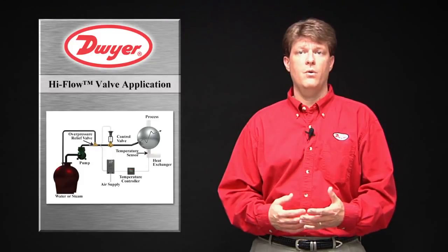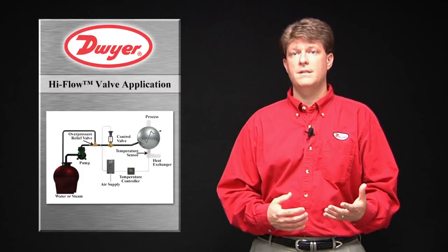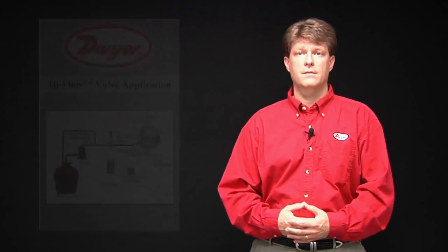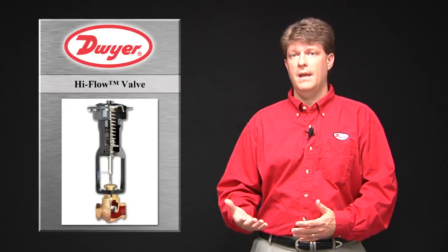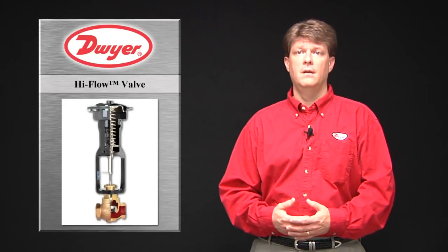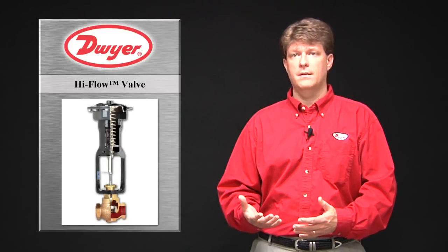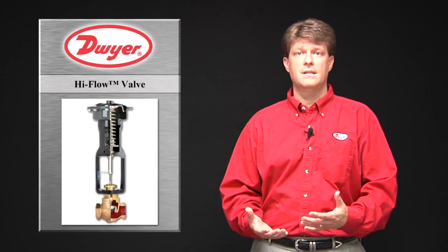In the example shown, a high flow valve is controlling temperature by varying the amount of steam or cold water added to the process. It is essential to correctly size a control valve for the application, or the process will not work effectively or efficiently. A control valve is always selected according to the application flow requirement, not the line size that it is installed in.